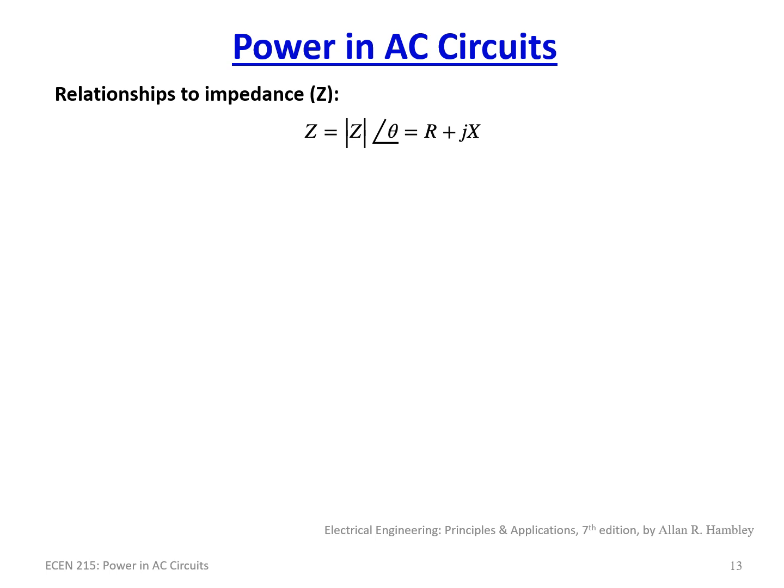So here are some relationships to impedance. We have the magnitude and phase angle of our impedance. And of course, impedance can also be in real and imaginary form. So again, polar and rectangular. I emphasize over and over again, I know I've mentioned this several times, it is very important to get used to working back and forth in the two different types of phasor relationships. The phase angle and magnitude are known as the polar form, and then there's the complex form of the impedance in a real and an imaginary form, where R is the real component and X is the imaginary component of the impedance.